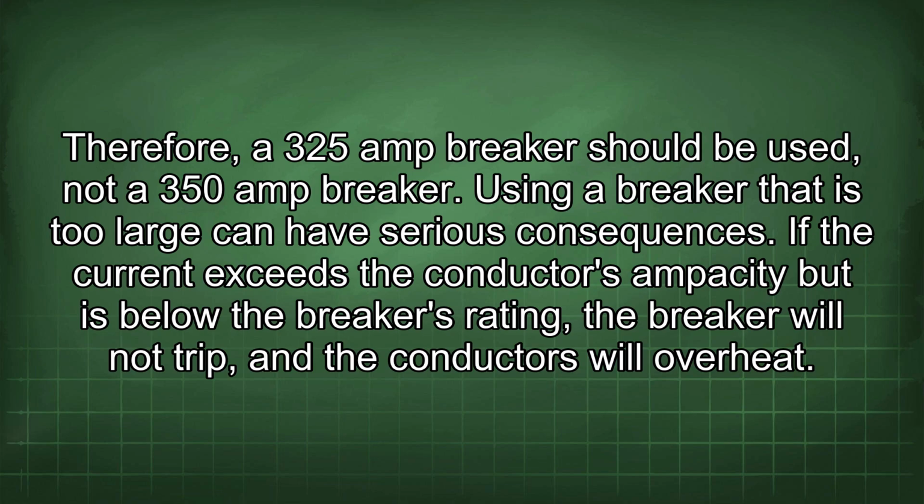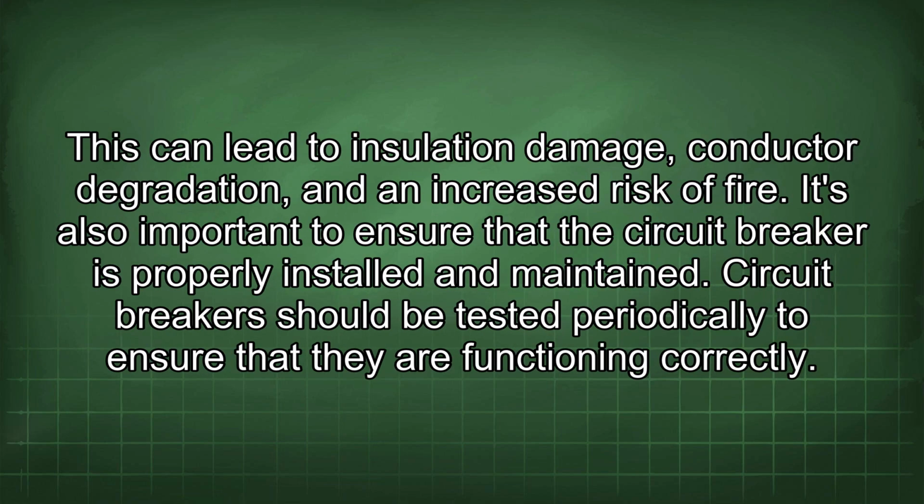Using a breaker that is too large can have serious consequences. If the current exceeds the conductor's ampacity but is below the breaker's rating, the breaker will not trip, and the conductors will overheat. This can lead to insulation damage, conductor degradation, and an increased risk of fire.